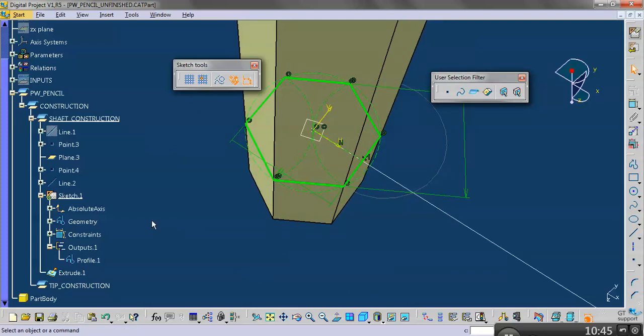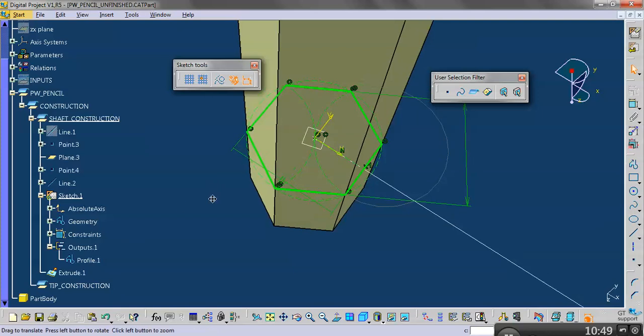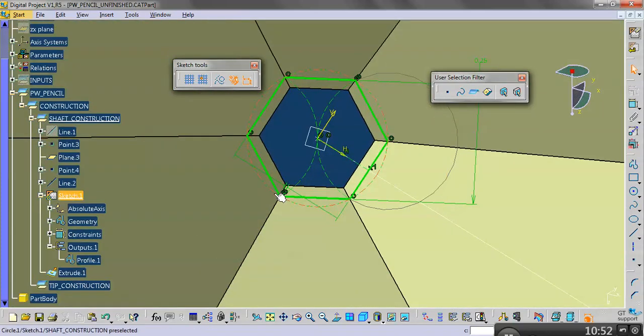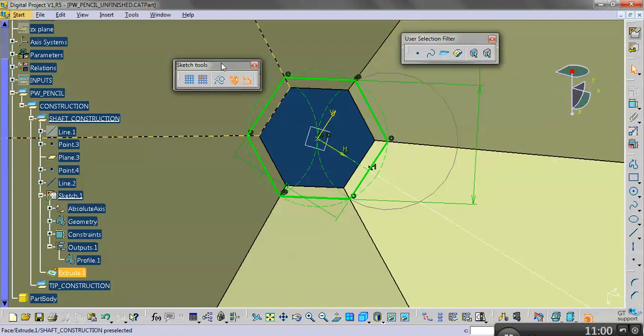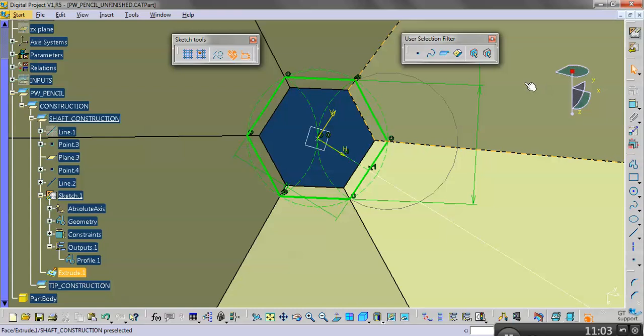Okay, so everybody double click on the sketch. And you probably zoomed in, reframed parallel to the sketch plane, perpendicular to the sketch plane. So this is where we're going to make the circle for the revolve. We could have made the circle outside of the sketch, since we have all the support geometry we need. But we're doing it in the sketch, just because. Tell you what, we'll do it in the sketch and then we'll make the circle outside of the sketch too, so we know both ways to make a circle.